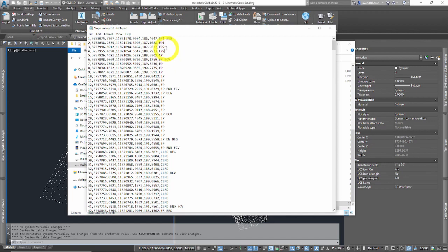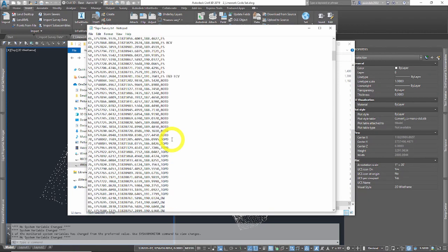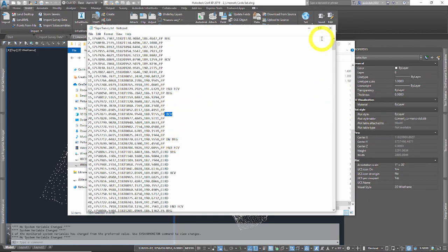There are different agencies that call these different things. This is additional code work to say this is the beginning of a line. This is going to help us in our line work code set to make the line the way it should be. And notice some of that. This one means end of line, and also something else. I believe it's the end of a curve, and it's a polyline. Beginning of a curve. And these are spelled out in our line work code set.